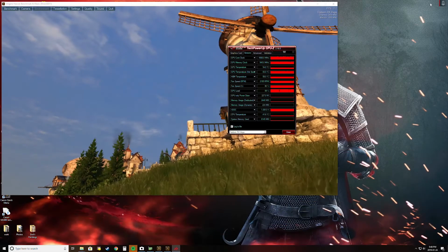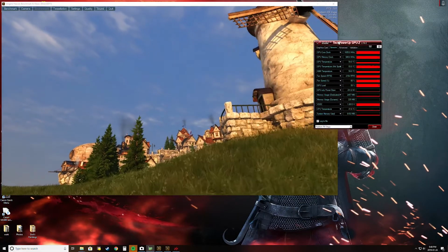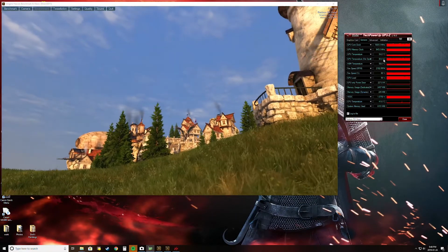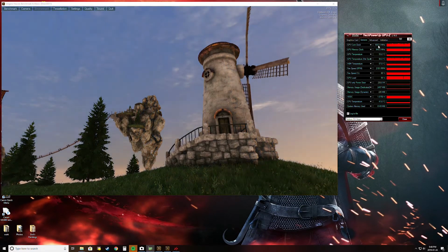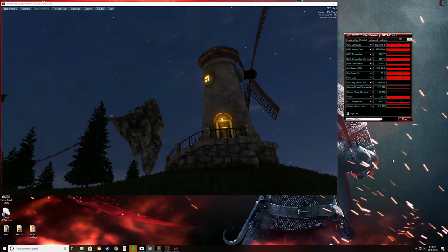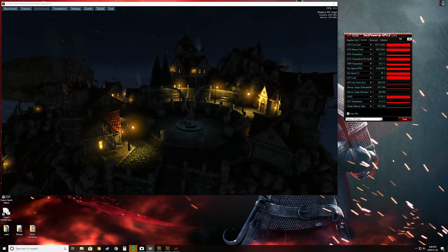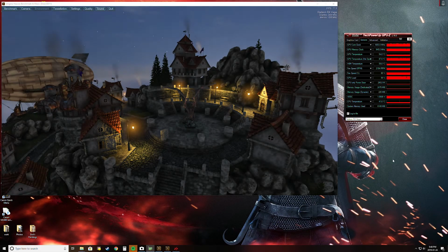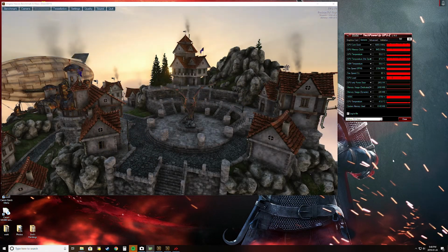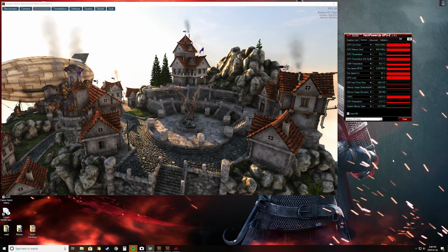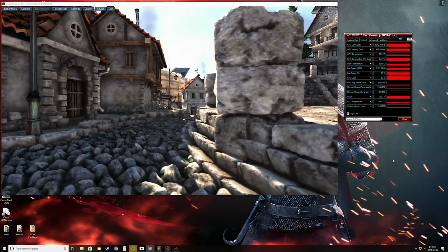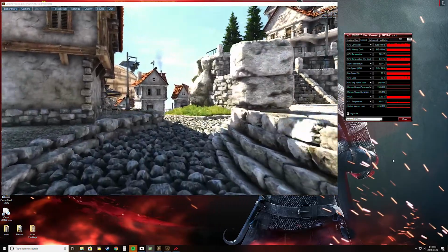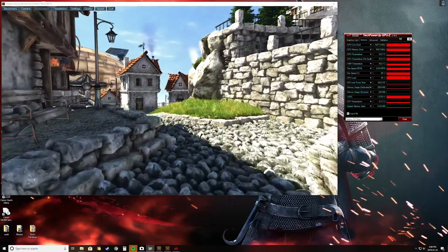Okay, and that's sort of the fundamental of overclocking your GPU core. And as you can see, the program's still running in the back. The temperatures are still good. We're almost at 1670 megahertz. I mean, I would call that a successful overclock. We're about 200, 240 megahertz faster than we were before we did anything. So certainly you're going to get better performance. It's running cooler and it's using less power. So those are all wins.